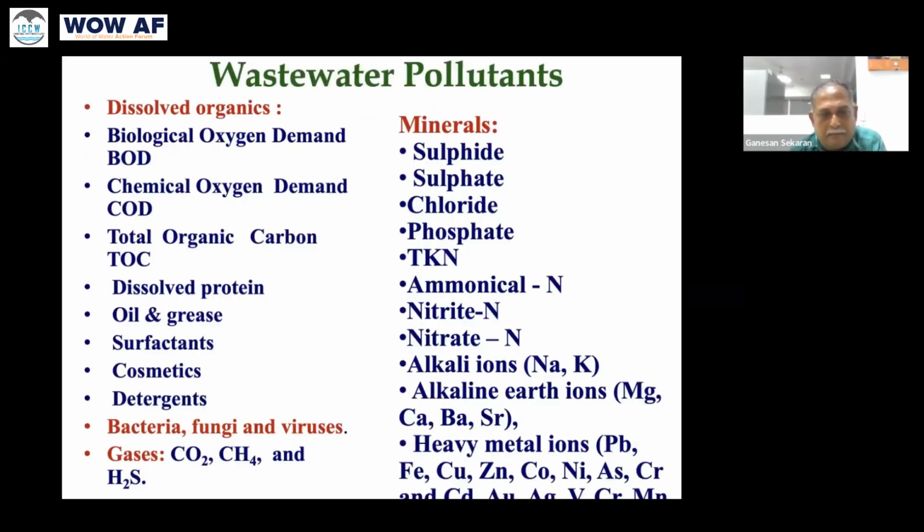And of course, the Adyar River and Kosasthalaiyar River have been contaminated due to the presence of heavy metals discharged from the sewage. Not only that: biochemical oxygen demand and chemical oxygen demand can be treated or purified by the water stream itself. But because of the presence of high TDS, they are not able to recover. The DO content of the sewage is very, very low. Previously, they used to have many types of fishes in these rivers, but now we don't see fishes in the rivers. Mainly due to this, the DO level is very low, and the dissolved sulfide concentration is very high in the rivers collecting this sewage.